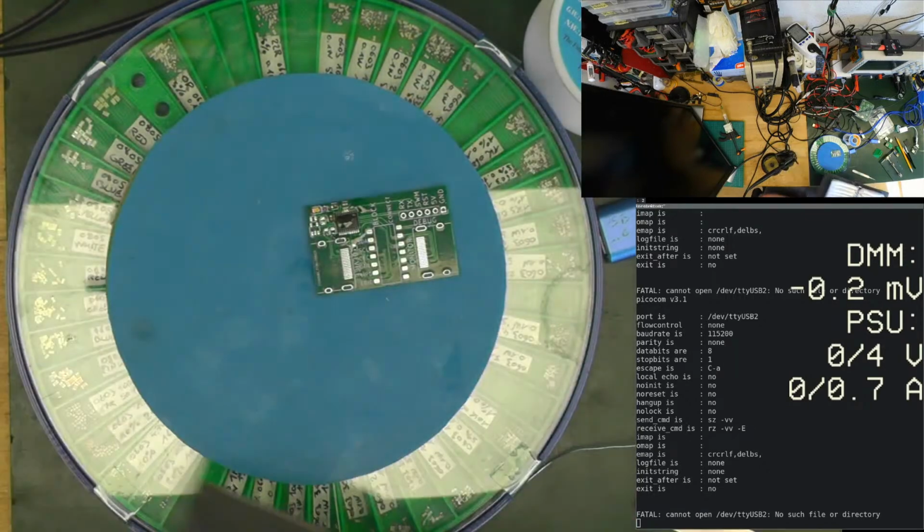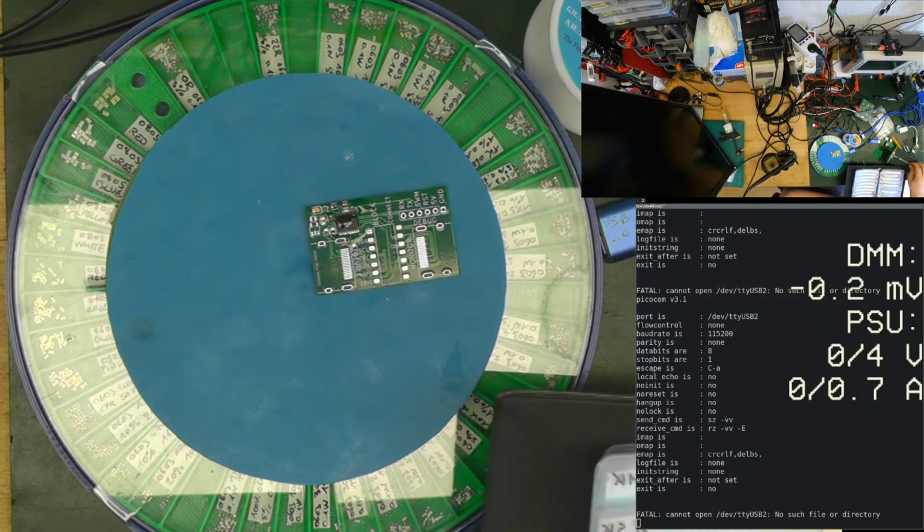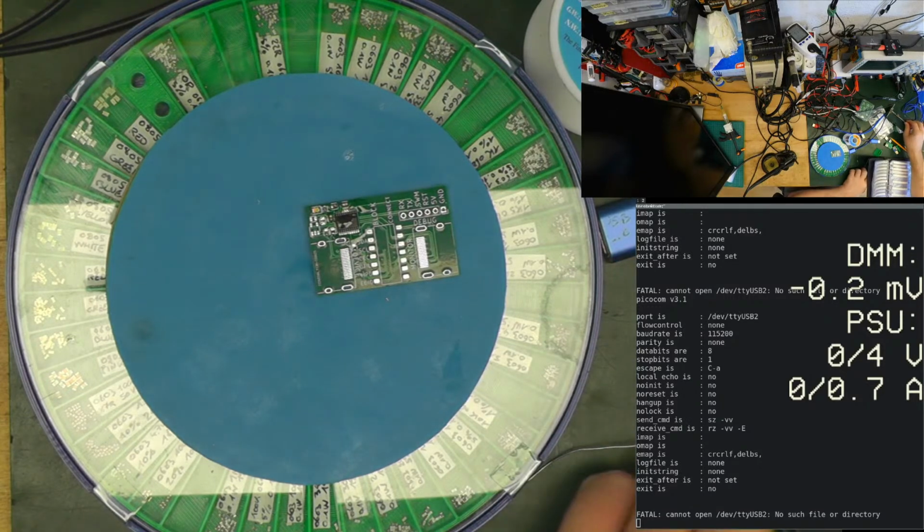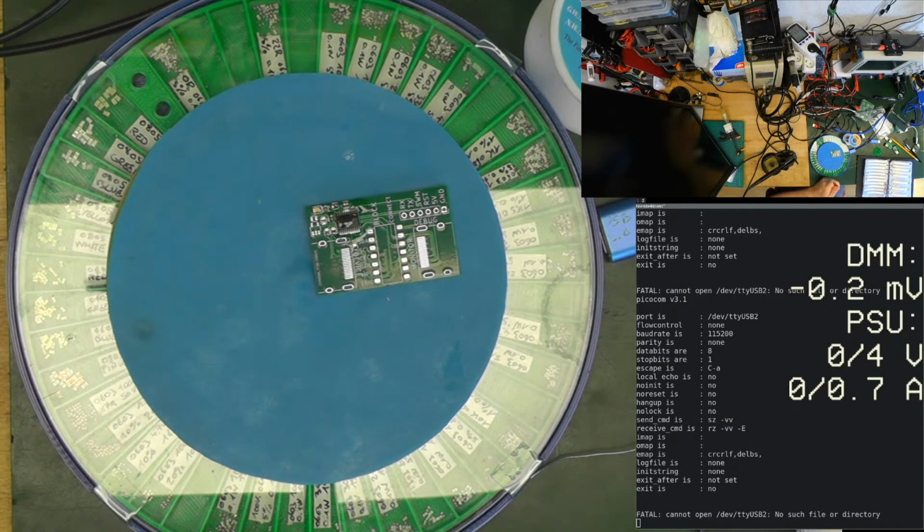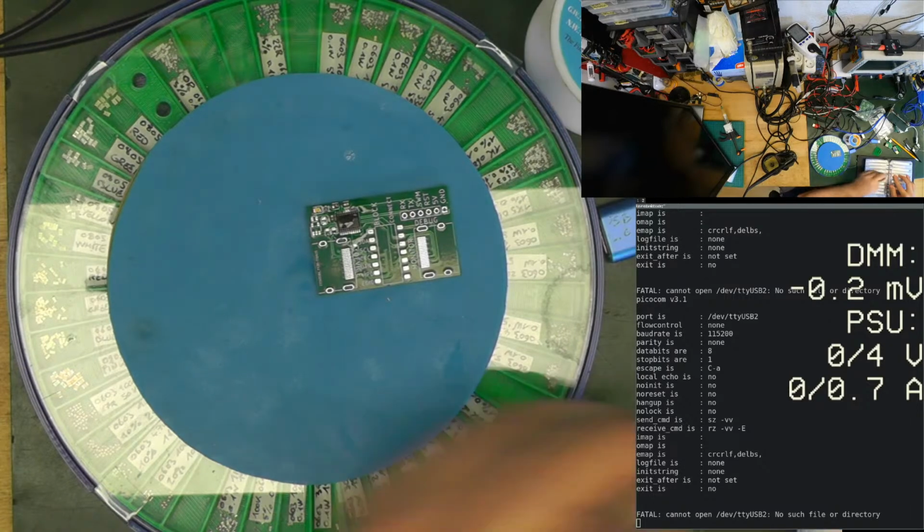This is closer than 34. And it's plus minus 20%, I think. I don't remember. Is this 20%? 47, 20%. Yeah, it is within 20%. So this will be correct. It's even within 10%. So let's use this 51K. We will be spec compliant.